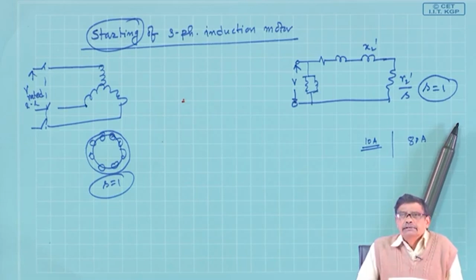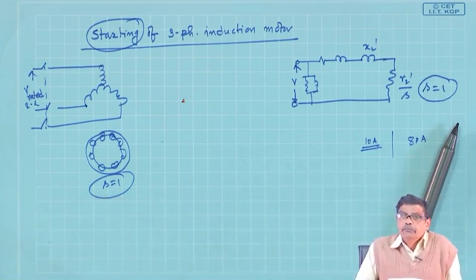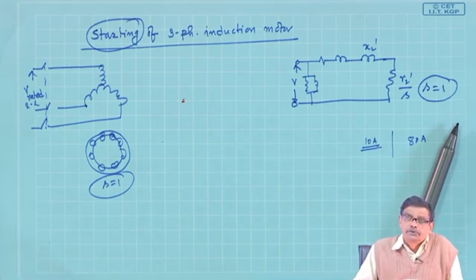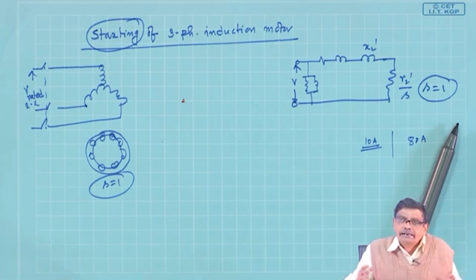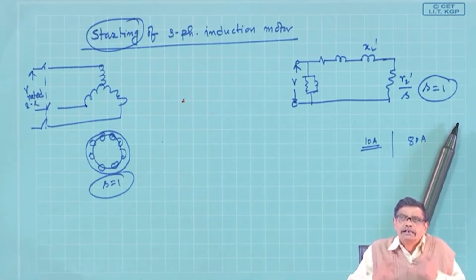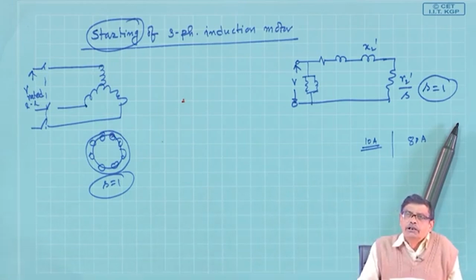And not only that, that is from the motor point of view. It looks like then, if the motor is very large with large diameter, say a 100 kilowatt induction motor, 440 volt, whose rated current itself may be say 50 ampere, you apply full voltage, then 8 times of that is 400 ampere, and you know large inertia means what? It will slowly start turning, gradually its speed will increase slowly. Therefore, a situation like S equal to 1 will prevail for a longer time.